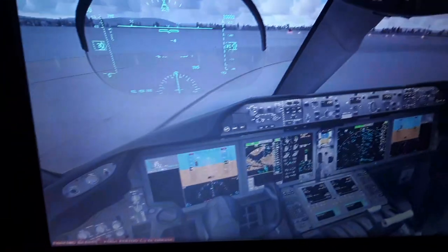So we have our own airport right now, the Zurich International Airport, the LSZH in Switzerland. We have the other airports around us. The range, we have also the VORs, ADFs and DMEs, the waypoints which are horizontal and vertical navigation fixes the aircraft can fly through. So you will see we're going to select some waypoints during this flight, so you're going to see them displayed over here in the navigation display.